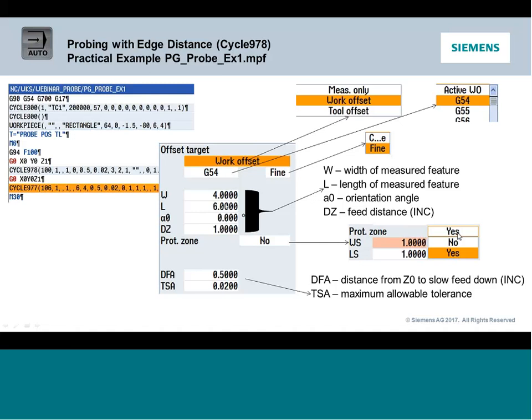This way, because this one's going to do a bunch of positions, right? I'm going to have pre-positioned it roughly in the center of the feature. So if you look here in the part program, we've got a little rapid move just prior to 977. And then it's going to automatically measure 4 sides. So it's going to go this distance plus a parameter that's been preset that will give kind of an overrun distance. I can give it an angular offset if I know the feature is tipped at a big angle.